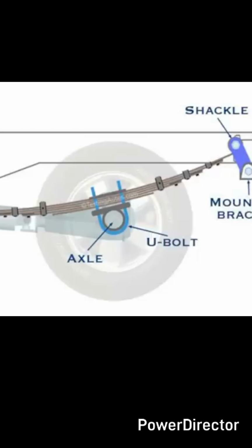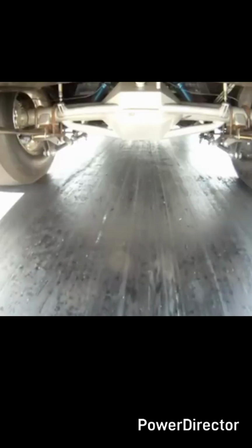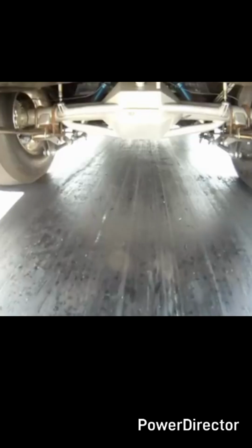The center portion of the leaf spring is attached to the rear end axle housing with the help of U-bolts, and a rebound clip holds all the springs together. This type of suspension is used in trucks, intended for more severe operations, and with a rear axle with high payload.